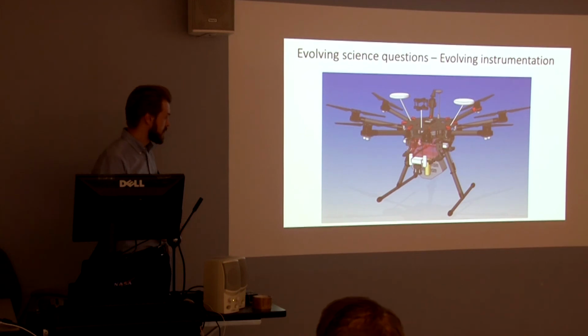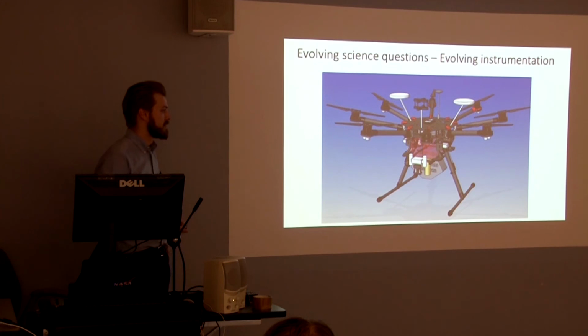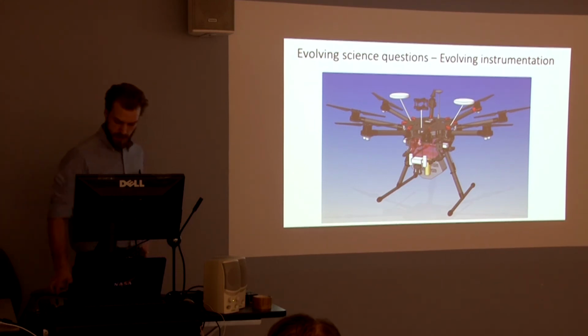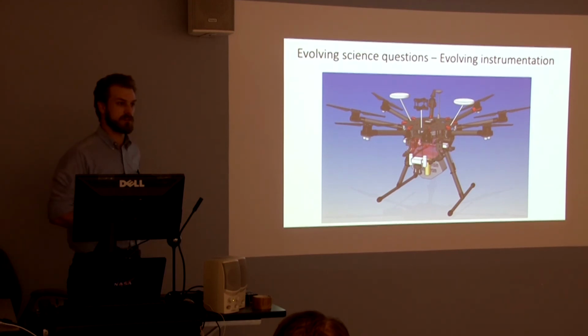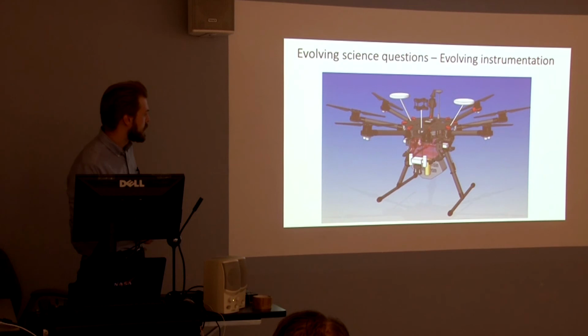We've got ultrasonic sensors that we sometimes position on the ends of each of these arms that allow us to know when we're approaching something, and it'll back us off. We've got a sonic anemometer that we're working on, which is part of a total weather station that measures 360-degree wind speed and direction. It can also provide sonic temperatures, and that's like the radiometers, at 10 hertz, and probably missing some other things as well.